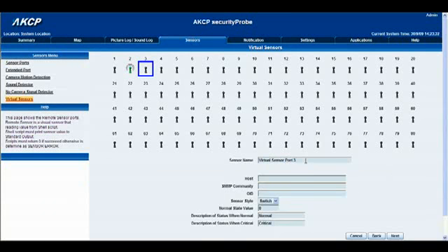Okay, so we will actually change the sensor name here to, let's change this to, sensor on, and then we'll put the IP 10.1.5.11, and then below that we have our host. Again, this is our IP address of that unit, so that's 10.1.5.11, and then we have our SNMP community.